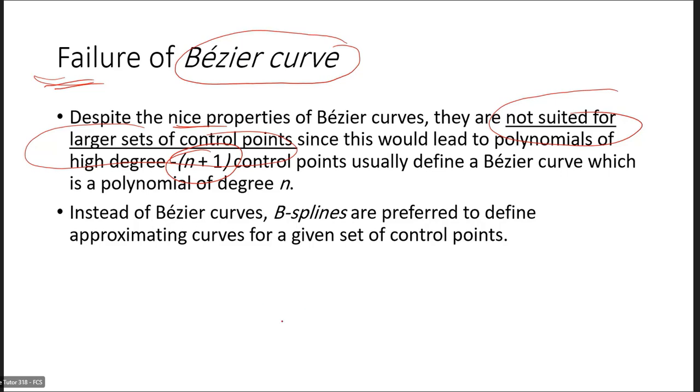That means if you have a curve like this, instead of making one Bezier curve with order 7, we can create a Bezier curve for the first part. And we can create another Bezier curve for this part, from here, 1, 2, 3, 4. And then I can join the two parts together. So this is one of the techniques that we can use.